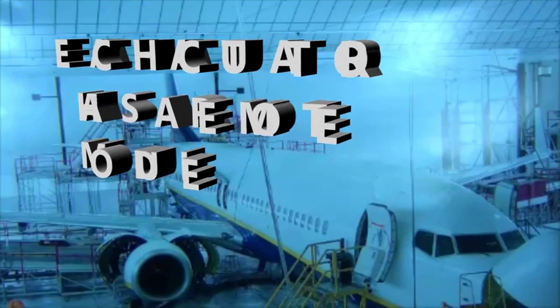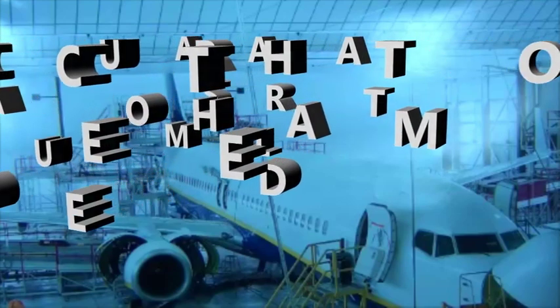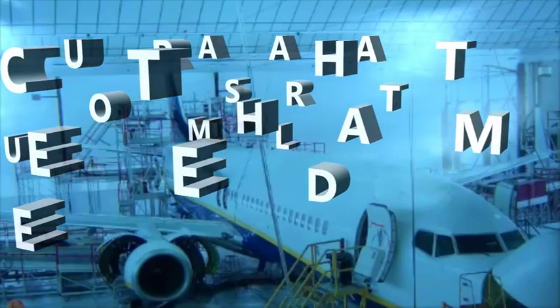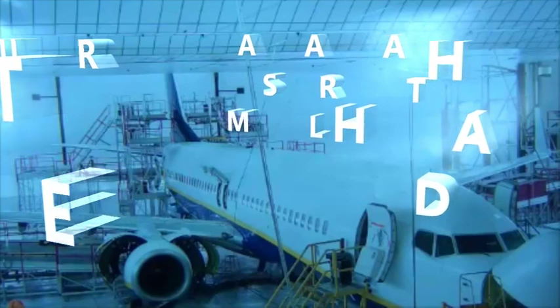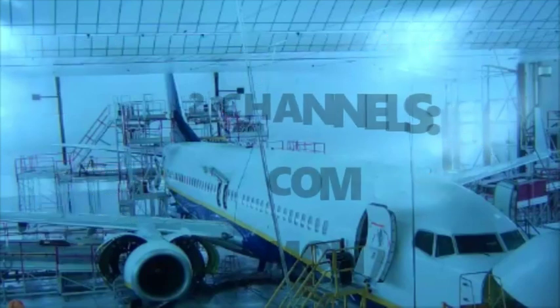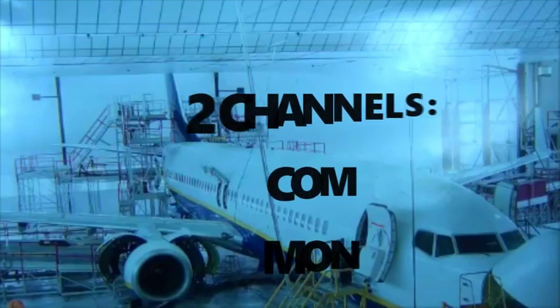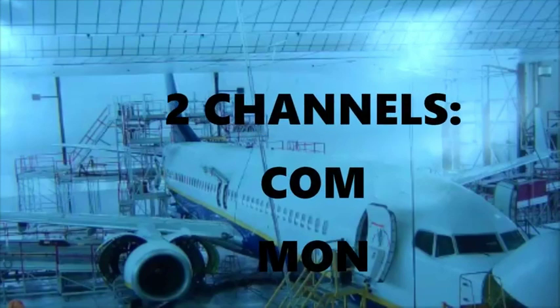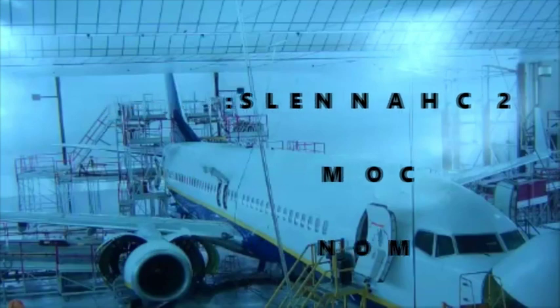That's just the same thing here when we talk about these modules, and they are connected to the actuators and of course to the computers. And here you've got the hydraulic and electronic sides of these actuators. Within these, you also have two channels. One is for monitoring, and one is for communicating. So it's giving command orders to get over to the actuators that are going to move the control surfaces.